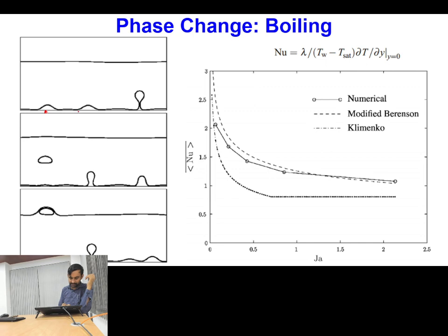This surface is given some constant surface temperature which is higher in comparison to the saturation temperature, and this is very high, so the boiling is getting converted into the film boiling regime. Here you can see this entire surface is covered with a layer of vapor, and in the zone where vapor is growing in size, because of buoyancy it is rising and pinching off some bubbles.